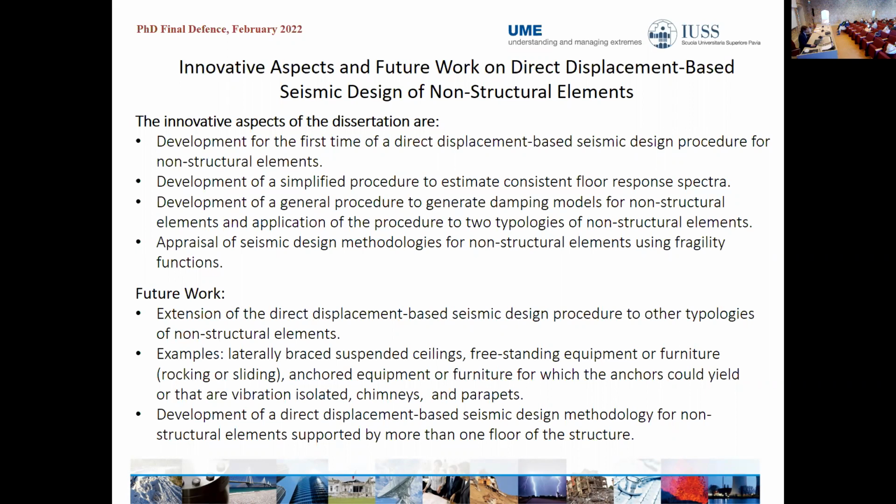Future work on this will be the extension of the direct displacement-based design procedure to other typologies of non-structural elements, like suspended ceilings, furniture, anchored equipment, vibration isolated equipment, chimneys and parapets. And then finally, the development of a direct displacement-based seismic design procedure for non-structural elements supported by more than one floor of the structure.